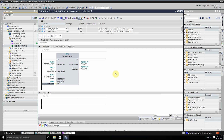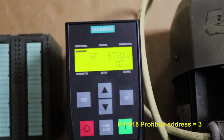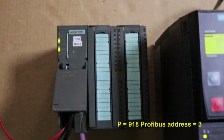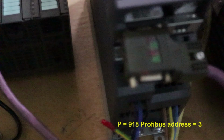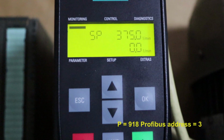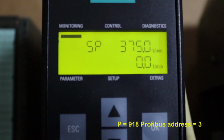As you can see that our communication has been established, but one thing that we have to set is the parameter 918, which is the node address, and we have to set the profibus address of the drive to 3 in this VFD. Okay, I have already configured this address to 3, and that's why communication has been established.